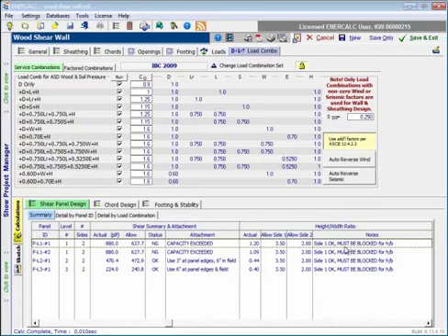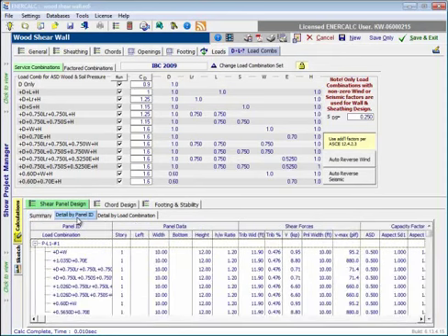We do note that it has to be blocked. The wall framing does have to be blocked for the height to width ratio that has occurred, but there is no reason why we couldn't use that height to width ratio. So some valuable design information here, and what we'll also see is that if we define a wall that requires an adjustment to the shear capacity, the unit shear capacity of the selected framing on the basis of its height to width ratio, the program will actually take care of that for us, and we'll see that when we move over to panel by ID.